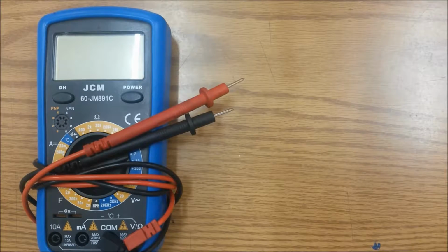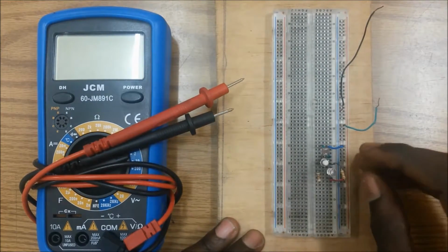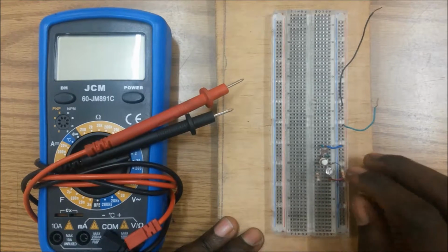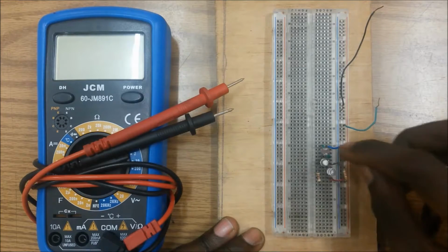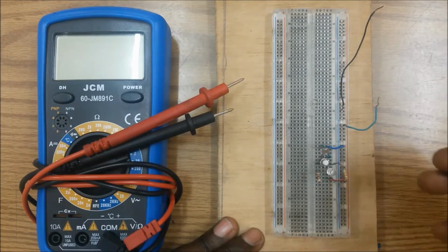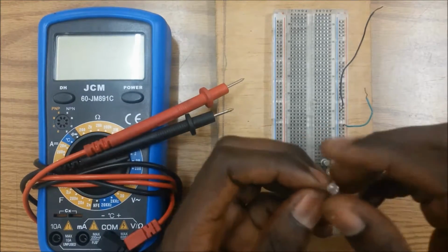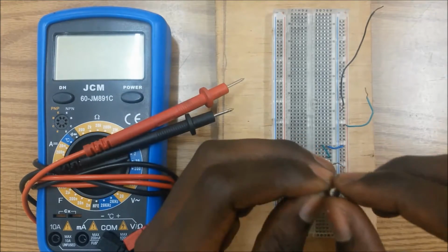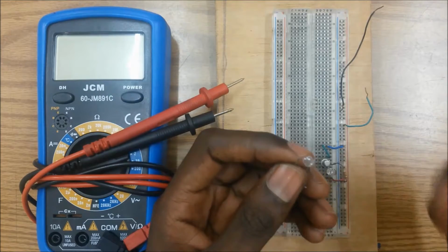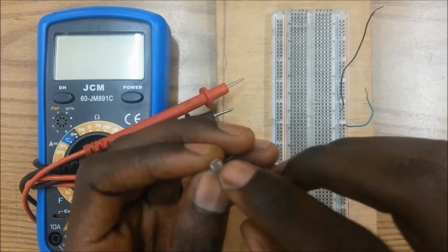Okay, so here I have a circuit with a couple of components. I have 3 resistors, a transistor, and an LED, which is a light emitting diode, and also some jumper wires to make electrical connections between those components. Now, this type of resistor is a special type of resistor. It's actually a variable resistor, and how it works is that the resistance of this resistor will fluctuate depending on the amount of light hitting the surface here.